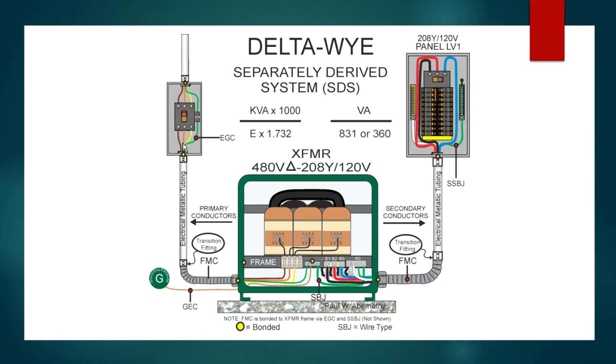Now, incidentally, if I were to take these conductors at the 90 amperes, if that's their current rating, and assume them at a continuous load, and size them at 125% of the continuous load, plus they are terminating in this overcurrent device, it corresponds with all of those rules in 215.3.